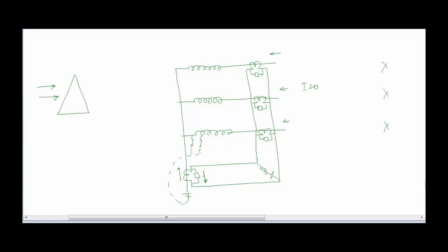Now this current is taking care of all the resistances or impedances which are connected in parallel to the circuit. So this current is giving current to this circuit, then it is providing current to the magnetizing path of this CT, this CT, this CT, and its own CT. So if the pickup of this relay was 0.1 amperes and the magnetizing current that is drawn by the CTs is, let's say, 10 milliamperes each, so 10, 10, 10 and 10, that is a total of 40 milliamperes.